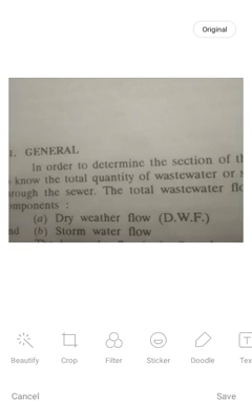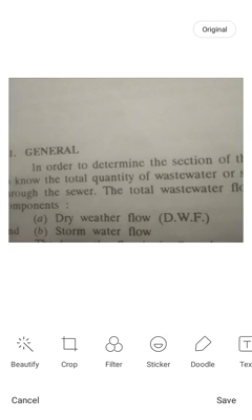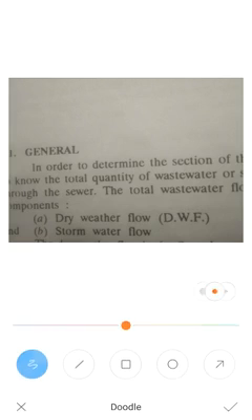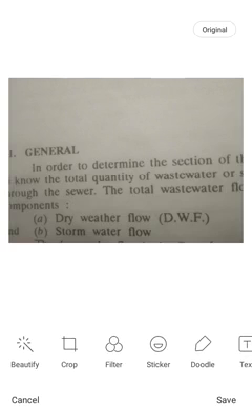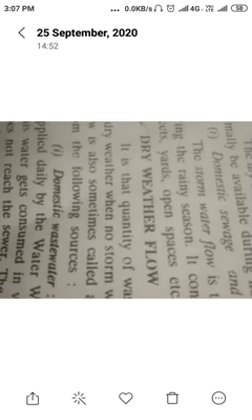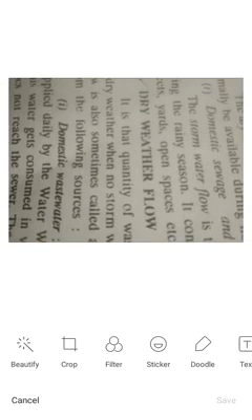First we will see about the domestic wastewater in the dry weather flow. As I told, in the dry weather flow the main sources are domestic and industrial, the wastewater from the public facilities, meaning public toilets, and groundwater infiltration, meaning from the ground it comes to the top. So that is also a dry weather flow. At summer time, the flow which takes place is the dry weather flow. We'll see one by one about the sources. The first source is domestic wastewater.